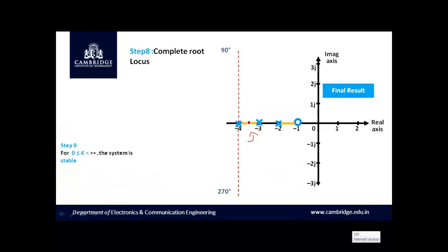And it is very clear that when making use of step number 1, P poles will be terminating at Z zeros. As we have 1 zero, one of the poles out of the 3 poles will be terminating here. And the rest of the P minus 1, that is two poles, will be terminating at infinity. One of the poles which is going to terminate at a zero is nothing but the pole which is located at s is equal to -2.